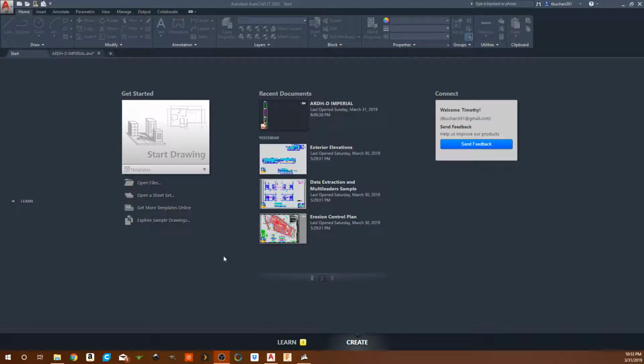Templates are just like regular DWG files with just a few key differences, and the biggest is that they are set up to a standard. By that, I mean it's already got all of your blocks and text styles and all that, and your paper space put into it. Where that is actually useful is if you're doing freelance work or if you're doing anything for a customer. It gives a sense of professionalism and uniformity, while for you, it actually just speeds up the process.